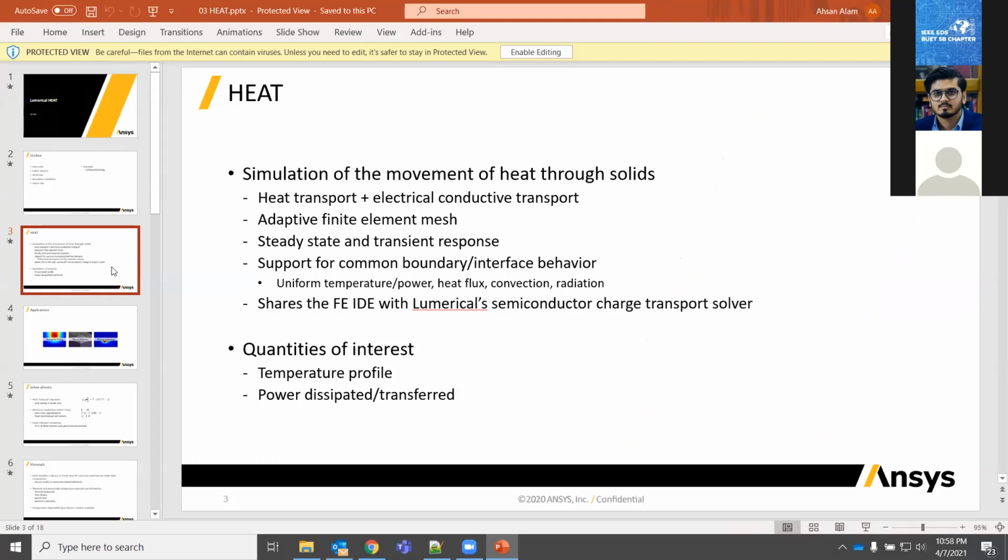If you have, say, air surrounding your device, which would be the case in most situations, or maybe some cooling liquids surrounding your device, you can still account for them by applying boundary conditions. Most importantly, like convection boundary conditions, you can apply them to the boundary of your device, and that way, if heat is escaping your system by convection through the air or by some fluid, you can still account for that. However, the actual simulation always takes place within solids.